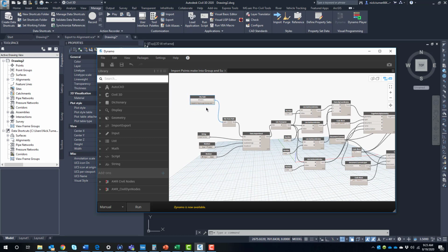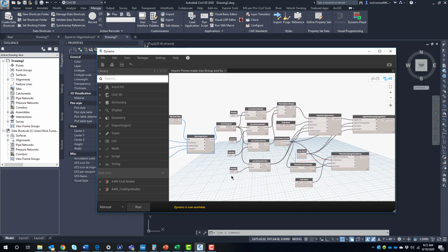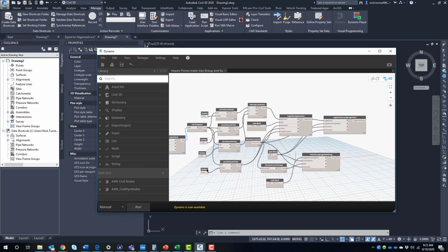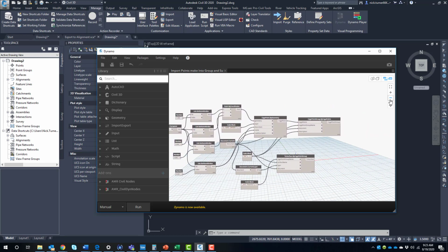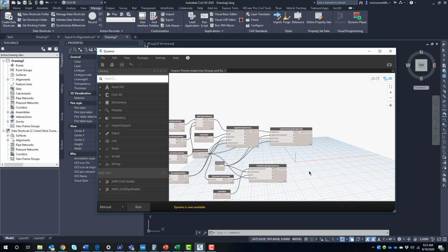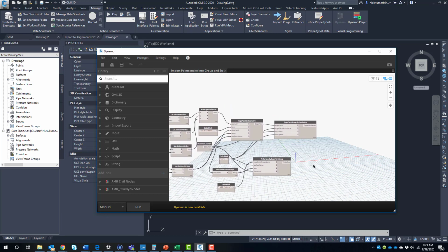So once again, remember, we're importing data into Excel. Just grabbing that file from the path. And then we have this data import Excel node. So it's telling us what sheet name, those types of things in Excel. Then transposing this list into get items, our code block, our points by coordinates, and coming through here to where we're going to create this. So once again, these things look kind of crazy with all of these lines and nodes and things, but it's relatively simple when you get going on it.